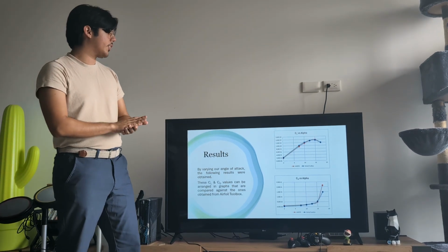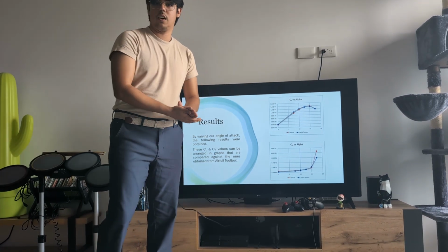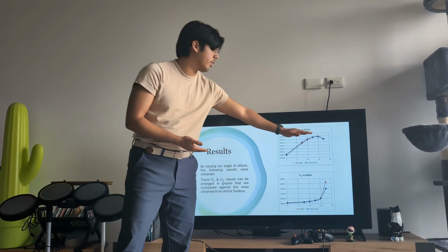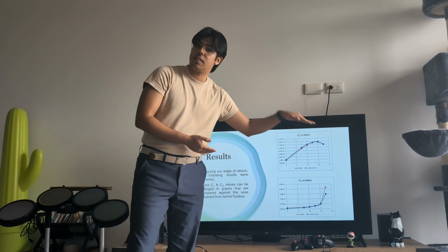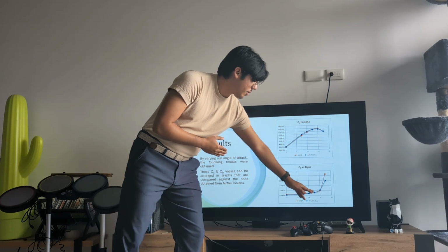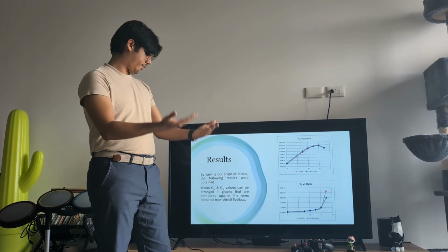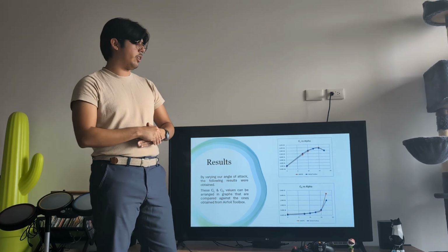As you can see very clearly, the lift coefficient is going steadily up, and then it reaches the critical angle of attack of 15, and then it begins to fall. And the drag coefficient is steady up until the 15-degree angle, and then it grows exponentially. Now, you can also see the